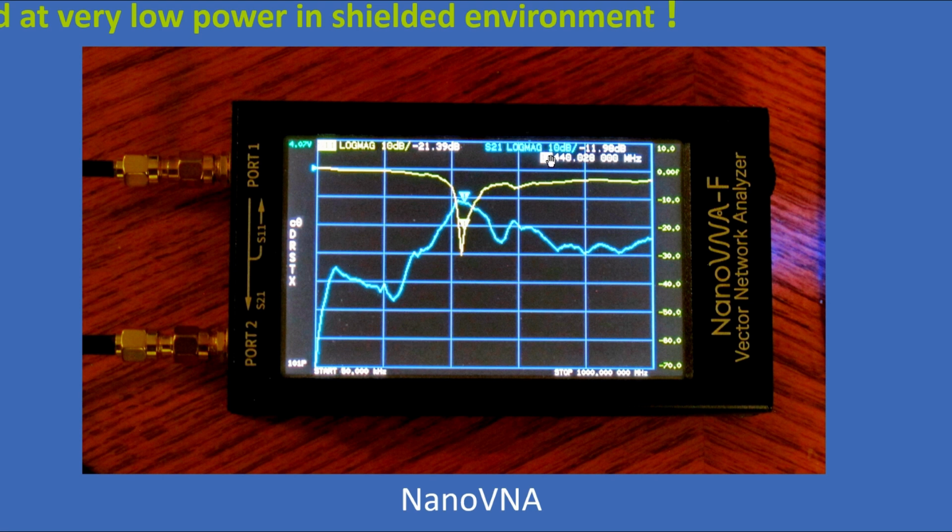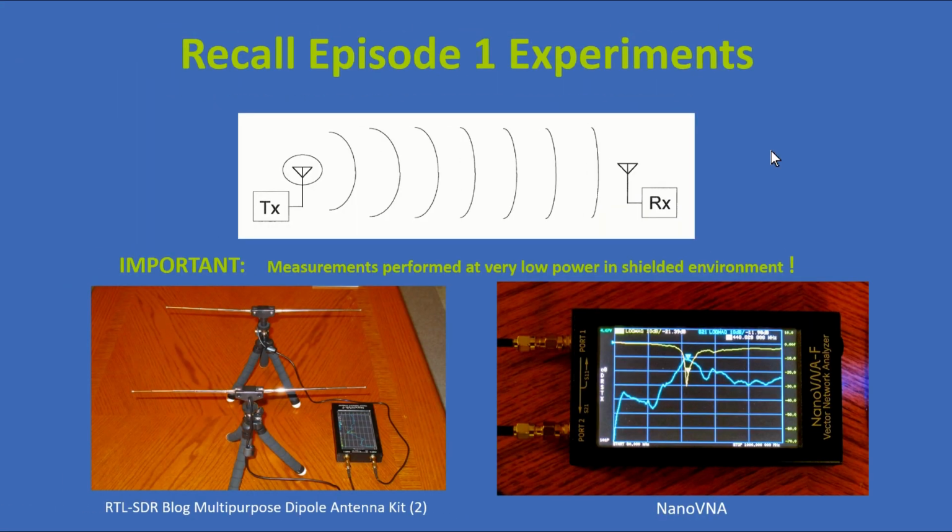There's a marker at 440 megahertz where the antenna is resonant. Now, the blue curve has a readout, and in the upper right it says minus 11.98 dB, which is basically minus 12 dB. What does that mean? Well, if you're familiar with dB, you may know that minus 10 dB would mean that we've received a tenth of the power that was transmitted, but this is minus 12.